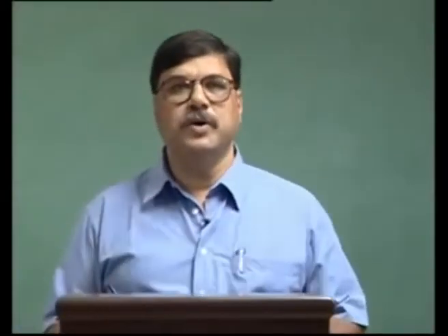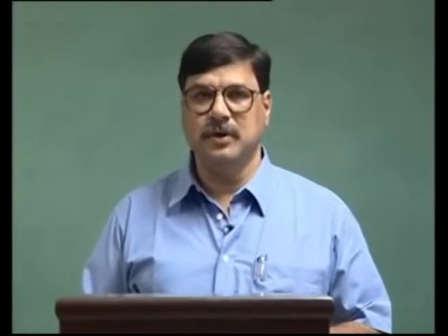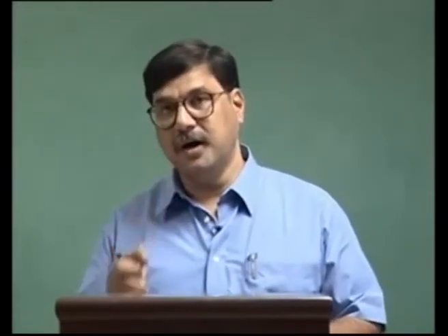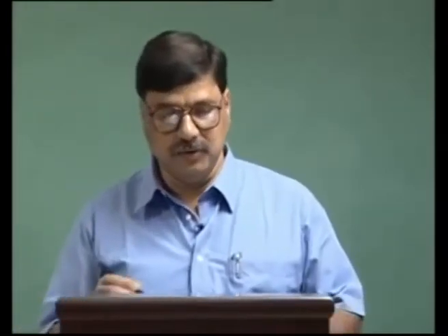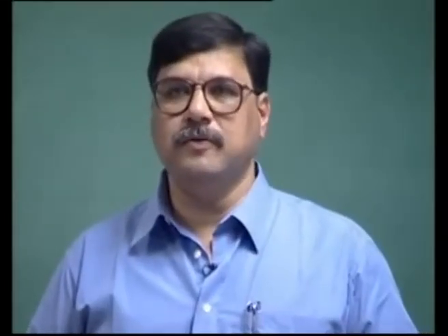In this lecture we are going to deal with a method of handling equilibrium of systems which are large and have a large number of subsystems. The method is known as the method of virtual work. To motivate this, let us recall how we dealt with equilibrium of systems such as particles, trusses, and so on.